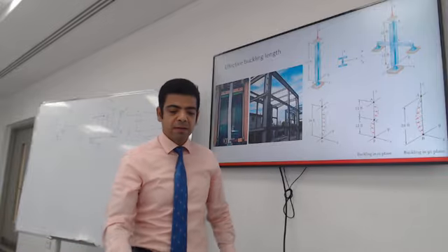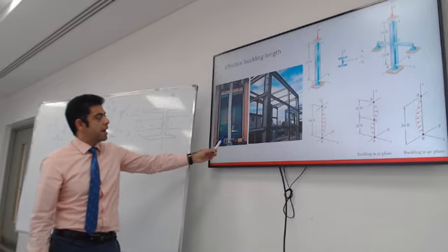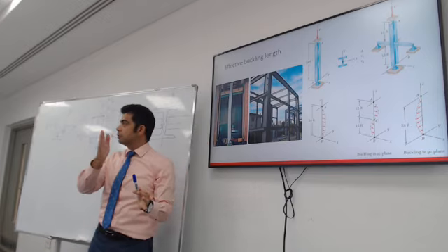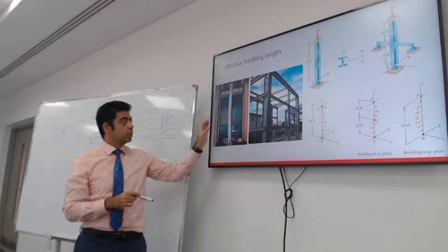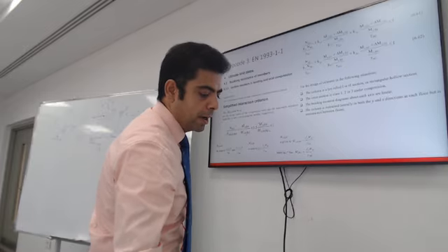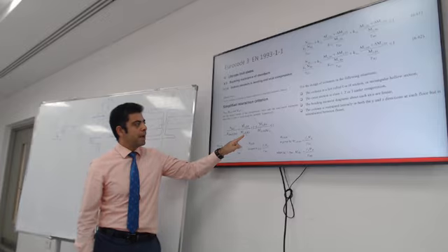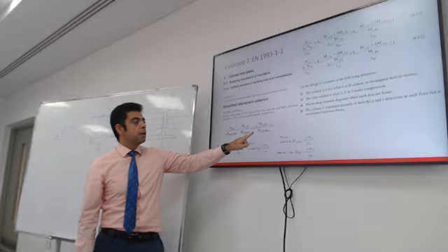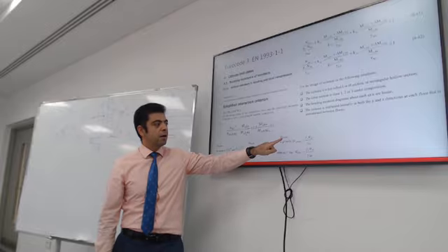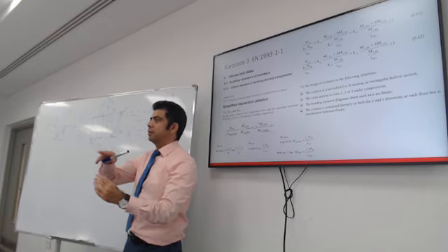Or bracing, yes, 100%. So what about a column like this? Just like a column that has nothing attached to it. Is this column laterally restrained or unrestrained? Unrestrained. So you will design it as if it's a beam that is laterally unrestrained. That's why you will find the factor that you compare moment about y has the buckling in it. You don't have to design the moment about z for buckling because the buckling usually is in the weak direction.